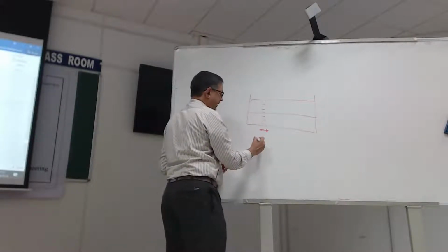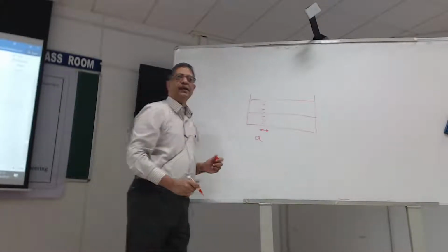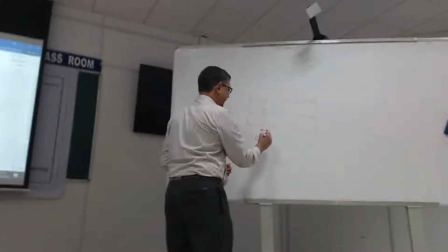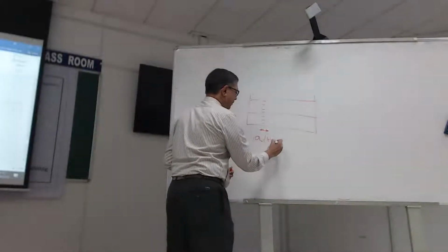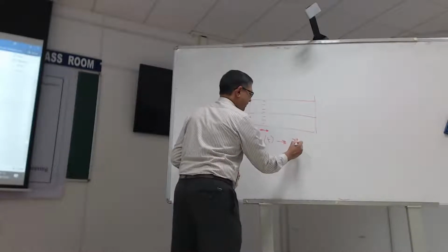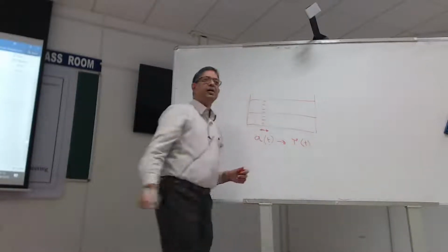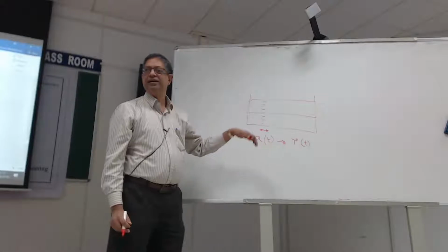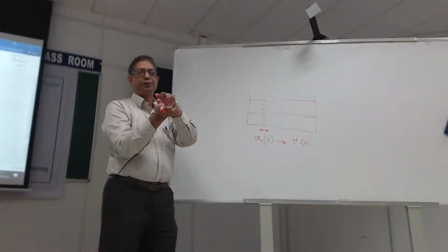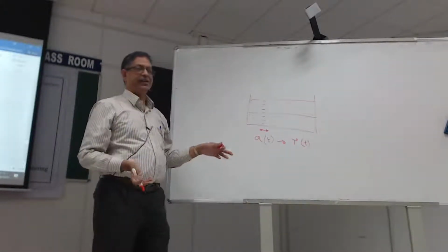If I know the accelerations at these locations as a function of time, I can work out the shear stress as a function of time, because I know the mass of each layer and I can work out how differentially it's moving. So I can work out the shear stress.